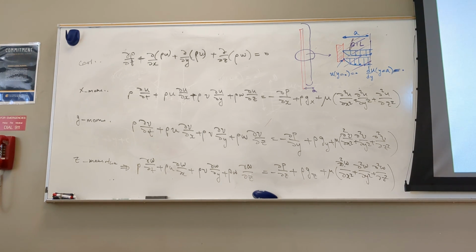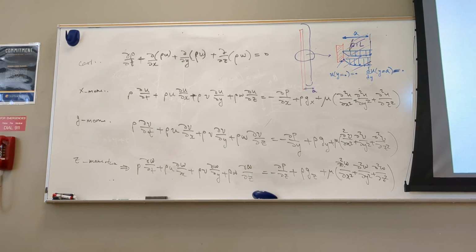You don't even see it. You have to wait 20 minutes so you see it going down. All right? So what can I say? If, in particular, I take the control volume around here, I don't care if it's going down, because the flow comes in the same pattern and leaves the same pattern around here. You see that? So in that case, is that a steady state? Yes, for that control volume.